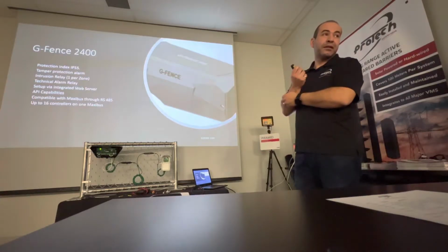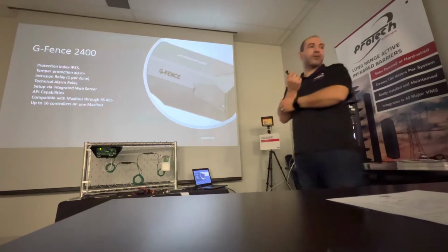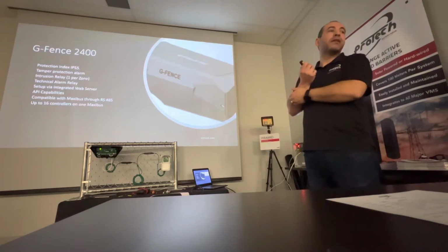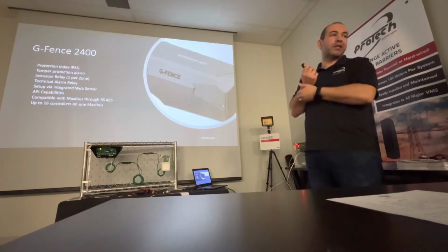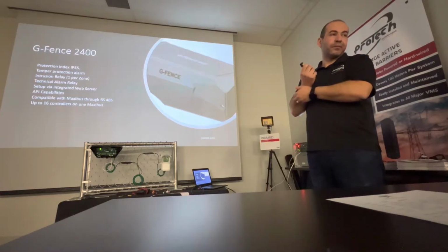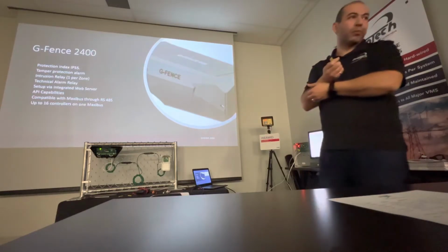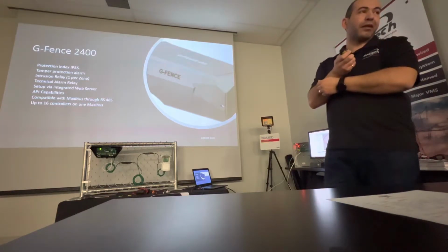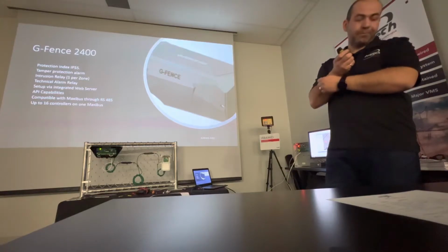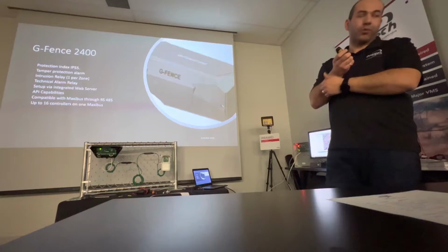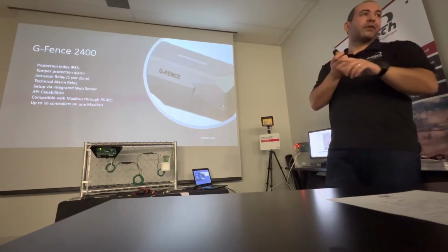You keep it inside and you ground it inside, and then you bring a ground out to make a common. If you put ground pins down, one here, one here, and here, you're going to have a problem. The potential will be increased in that case. Between this one and this one, all of a sudden you get voltage on the line. It's not a ground anymore. You have to common them out.